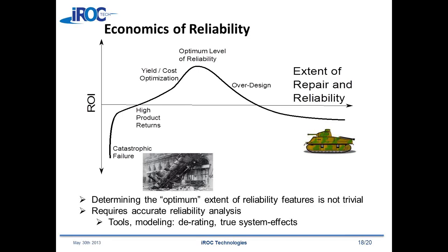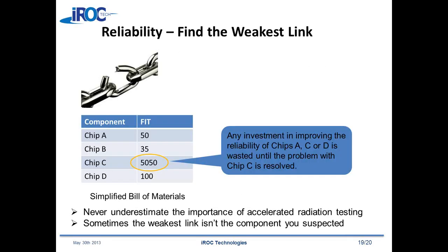And the other thing that I want to draw your attention to in terms of reliability, which is a little bit different from other areas, is a system is only as reliable as its weakest component, or the component with the highest failure rate. As a silly simplified example, imagine you have a card with 4 chips on it. If one of the chips has a FIT rate that's 50 times higher than all the other ones,